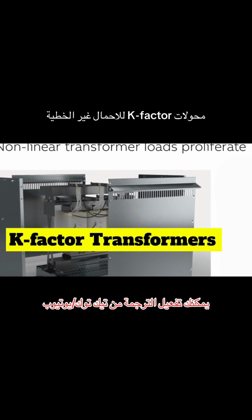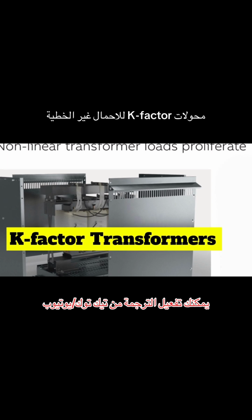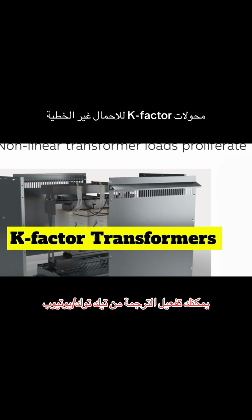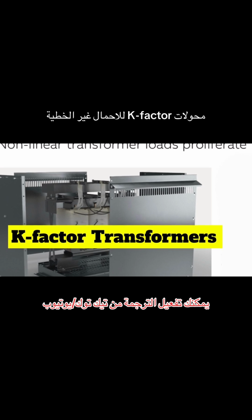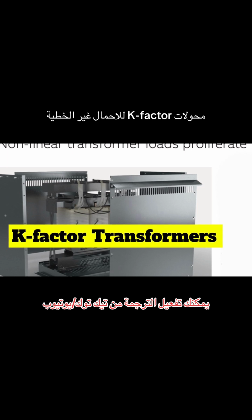So higher K factor equals tougher transformer. Exactly. A K factor of 50 is for the really extreme cases where you know exactly what kind of harmonics you're dealing with, like in very specific industrial applications. But more commonly, you'll see K factors of 4 or 13. These are the workhorses for handling moderate to significant levels of harmonic distortion that you find in a lot of modern buildings and industrial settings.